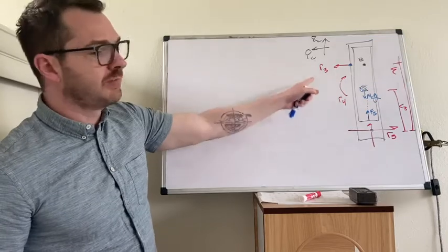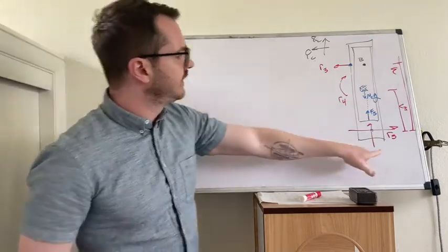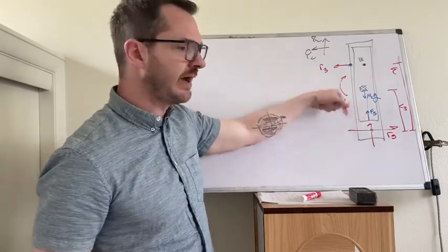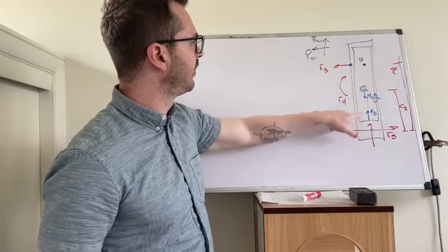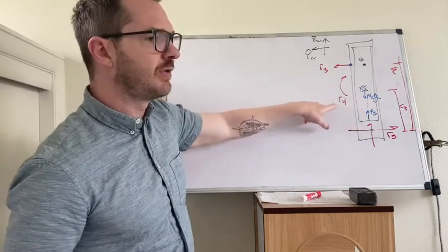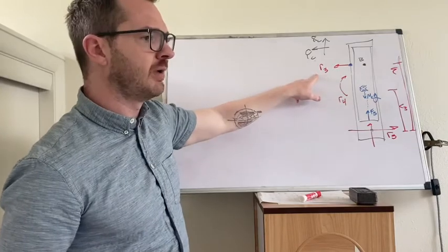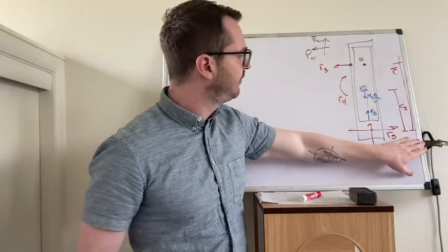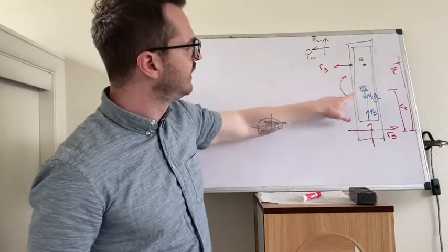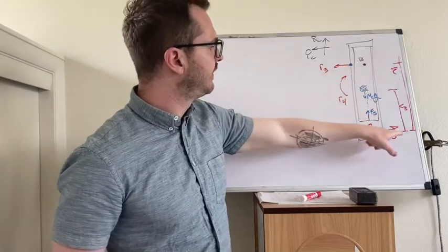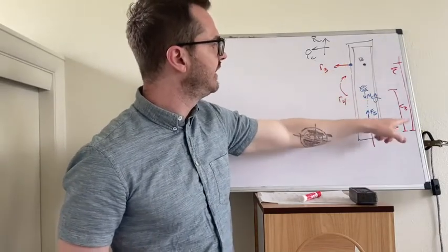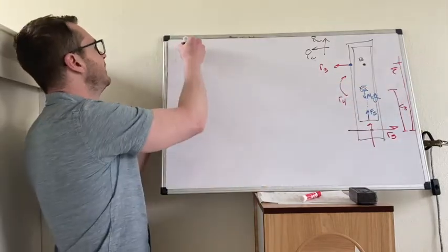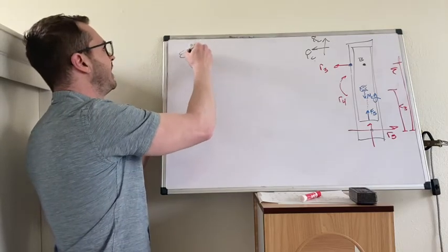Here's the free body diagram for body C, the slotted rod. We have reaction set 5. These are positive. We have the spring force. Remember, it was down on the sliding block, so it's up on the slotted rod. Gravity, R3 and R4, I reversed the directions from body B onto body C. I've also added the C frame, and I've added these two lengths. Remember, this was point D, point C, point B. So we have L3 is from D to C, and Q is from D to B. So let's do sum of forces on body C.